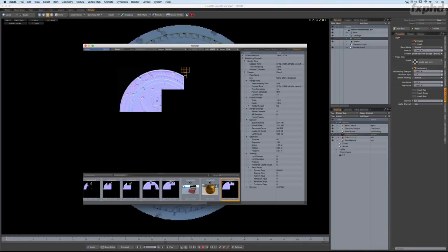Now, it can be a moment of frustration trying to figure out how far to shoot that ray out. So I want to show you cage-based normal mapping and cage-based baking. It's faster and, in my opinion, a much more accurate way of creating normal maps inside of Modo, and it's really, really easy. Let's just let this go through its process here.